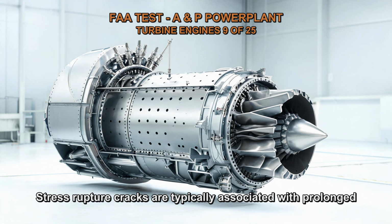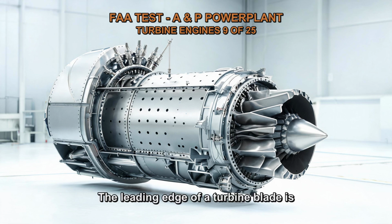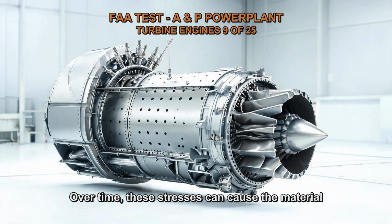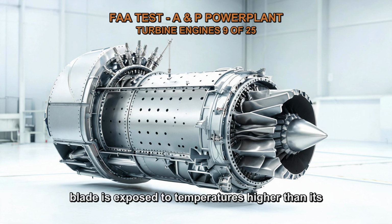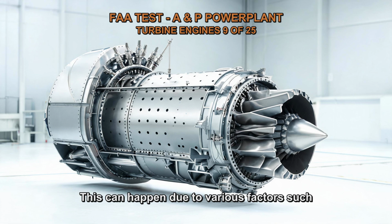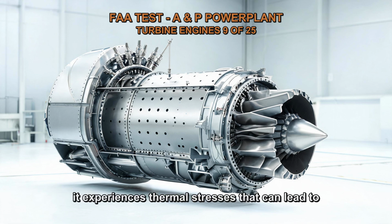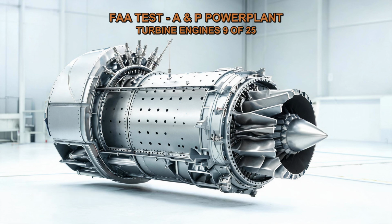Stress rupture cracks are typically associated with prolonged exposure to high stress levels and elevated temperatures. The leading edge of a turbine blade is subjected to significant thermal and mechanical stresses during engine operation. Over time, these stresses can cause the material to weaken and develop cracks. An over-temperature condition occurs when the turbine blade is exposed to temperatures higher than its designed operating limits. This can happen due to various factors such as inadequate cooling, combustion anomalies, or operational issues. When the blade is exposed to excessive temperatures, it experiences thermal stresses that can lead to material degradation, including the formation of stress rupture cracks.